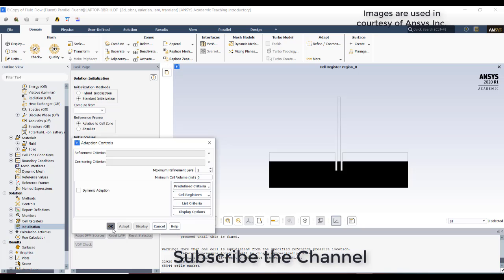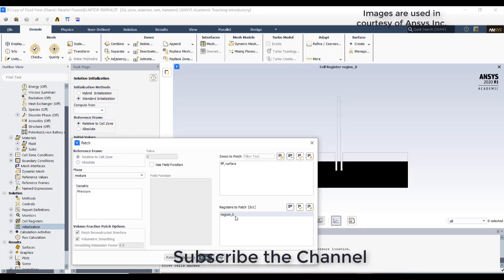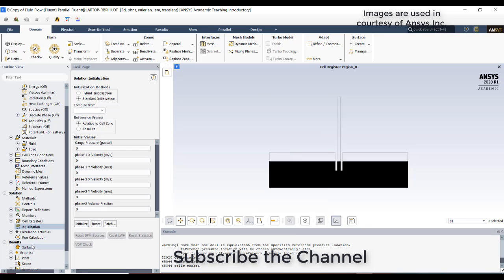You can just click OK, go to patch. We'll go to phase 2, volume fraction, and I'll try to patch that region with volume fraction 1. Patch it. So only this region is patched with a volume fraction of water of 1, and everything else would be air.